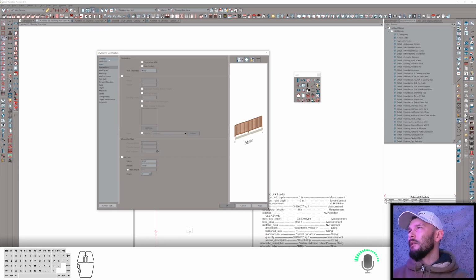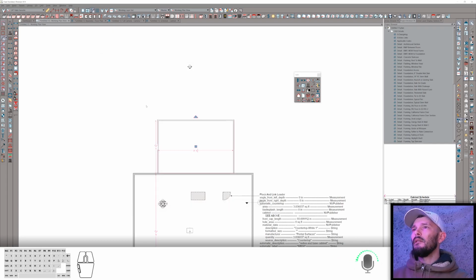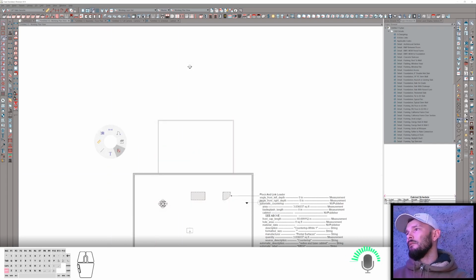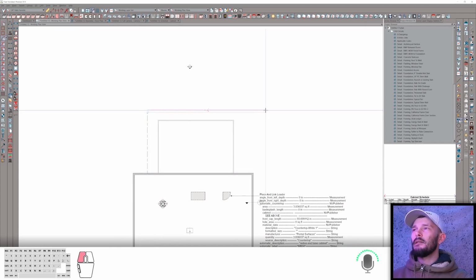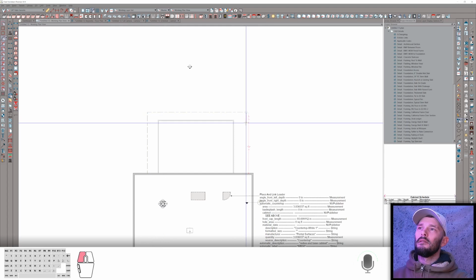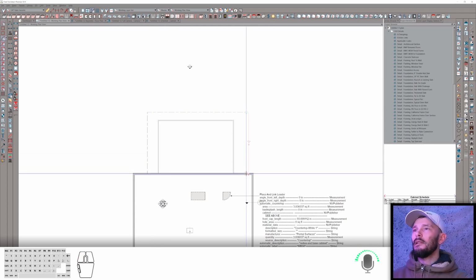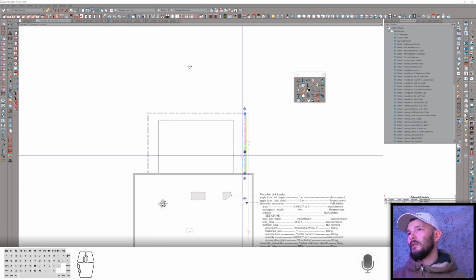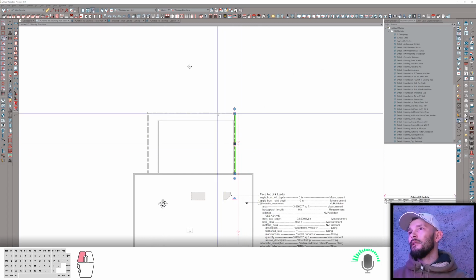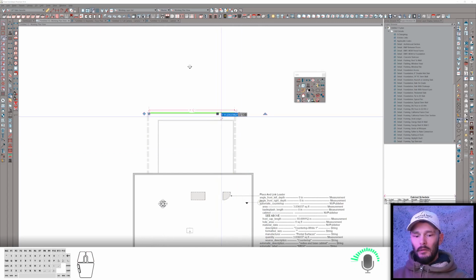There are a couple cases where we might need room definition, but let's just say no room definition, and then I'm going to use a room divider, and this could be 6 inches past the rest of that, and I could designate that this room has a slab, right? Pretty simple way of doing it.